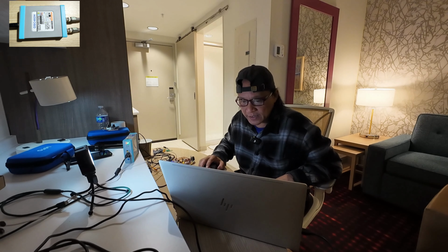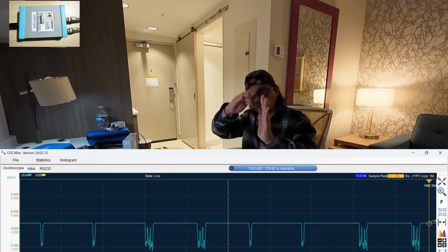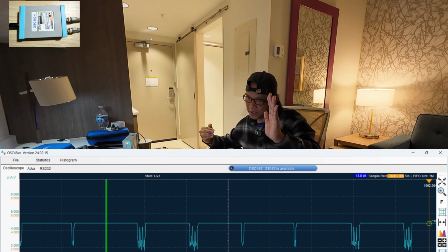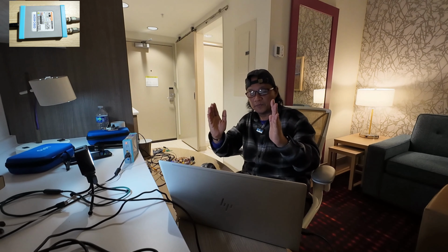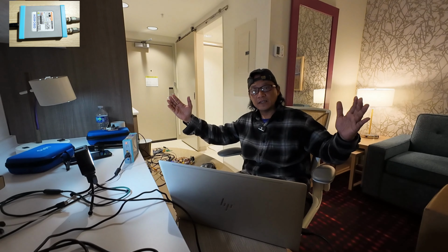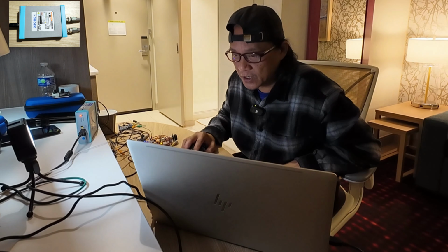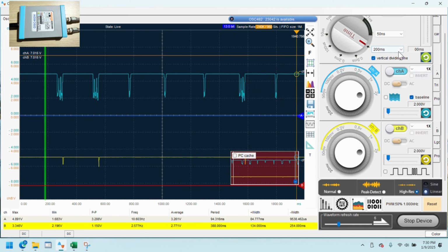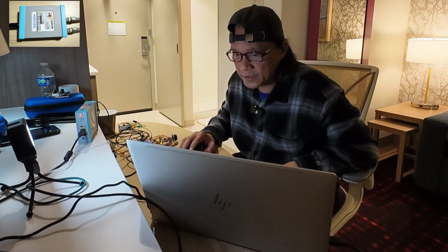So what I can do next is to set the trigger. I'm very specific to that signal only. The TX LED will show the waveform, and then the RX will come in, and then I just want to stop it when the whole process is finished. I'm not interested in the repeated cycles, just one. So I'm going to enable the channel A trigger. I'm going to put that at 10 milliseconds, and then I'm going to go to the trigger.